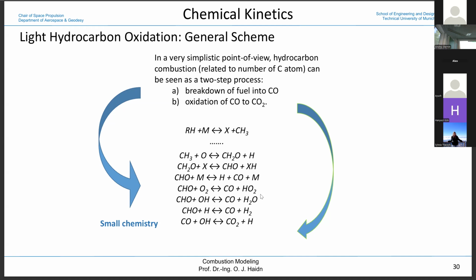And the reason is, typically in combustion processes, we have sufficiently high temperatures that even large molecules are not stable. They break down because of the collisions coming from all sides, cracking reactions. We break those into smaller units. We even have combustion models with some stochastic modeling of the larger molecules, but what we need is the small chemistry to be right, then we're doing a good job.